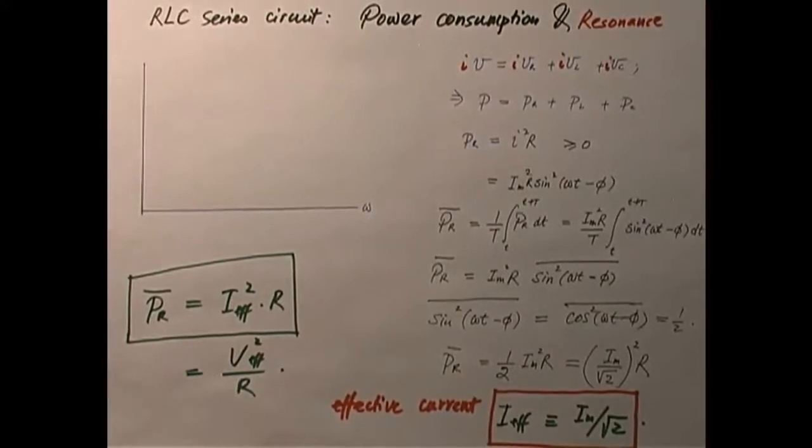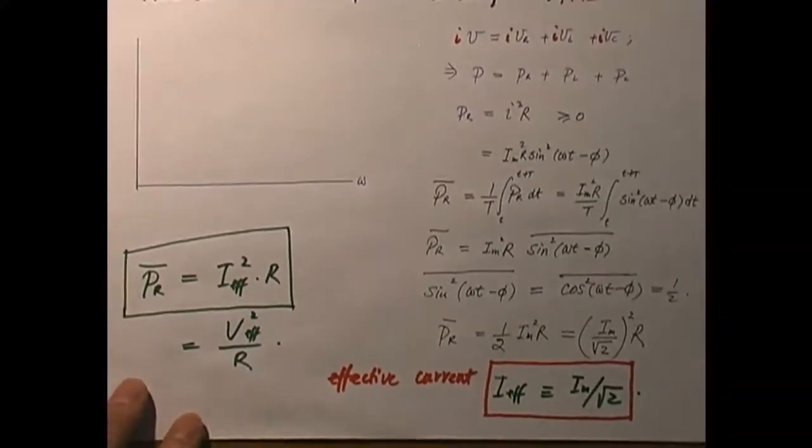Now we always say that the power outlet that we use here is 110 volts, right? That 110 volts, do you suppose it is the peak value or the effective value? Well, when people calculate the power consumption of a device hooked up to the power outlet, do they worry about instantaneous power? I don't think they do, because it varies 60 times a second. I don't think anybody's dumb enough to actually care about the instantaneous value. You care about the time average value, right?